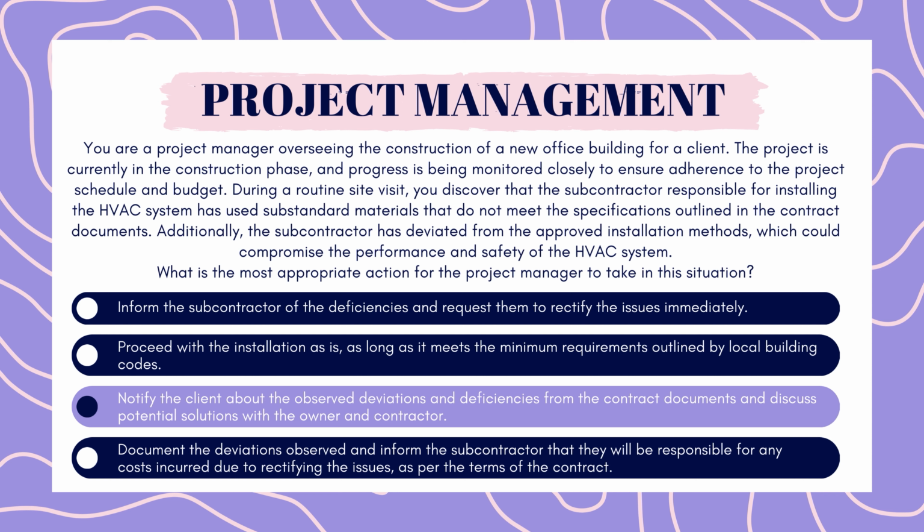I know, it's super frustrating, but on all of your exams, if they don't state the contract or the delivery method, then it's the traditional construction delivery method, which is design, bid, build, and they're using the standard AIA contracts that go along with that, like B101, A101, and A201. Keep that in mind, especially for project management and construction evaluation.